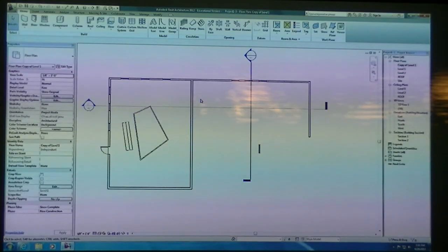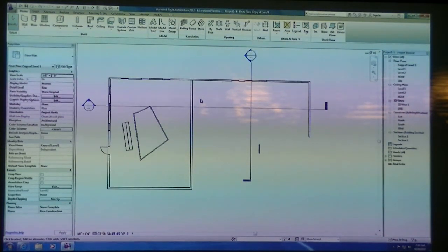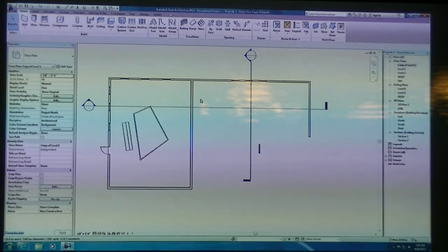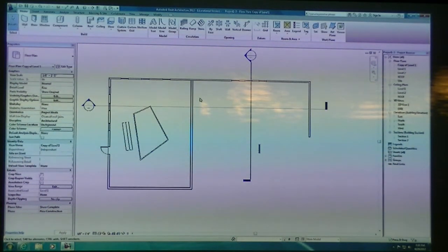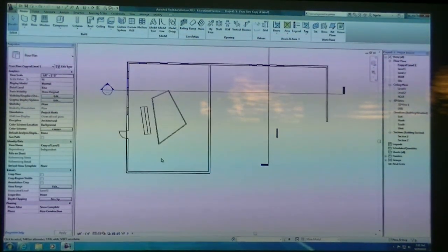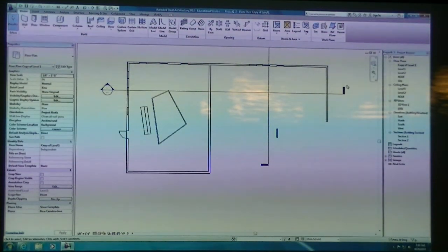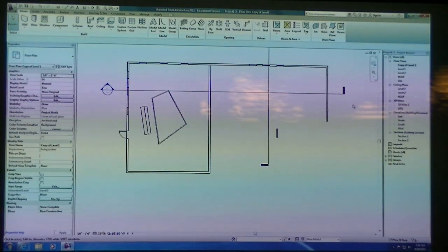Someone might continuously be working and doing updates to your one particular file, and as soon as you do a save as, you're breaking that connection with everybody else, and you're modeling on your own, and nobody's realizing what's happening with your different options. Because you might want people to still model the rest of the building or work on the existing. So there is an option here to create what are called design options. And design options are also view specific, and they're a way of toggling your different options.